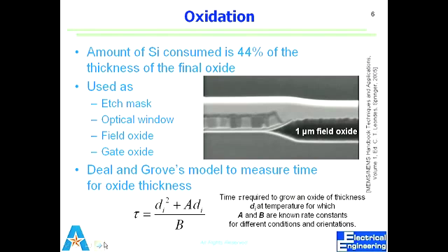I can do etching in silicon using this as a mask, whatever recipe I use, whatever chemical I use for silicon etching, right? That's called an etch mask, right? If I use something like this, we call it a hard mask, which means a layer of a material which is hard, in very intimate contact with the material, grown on top of that material and adhering very well to the surface. Use that as a hard mask.